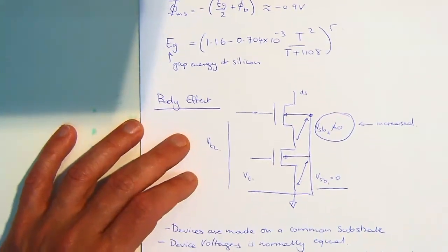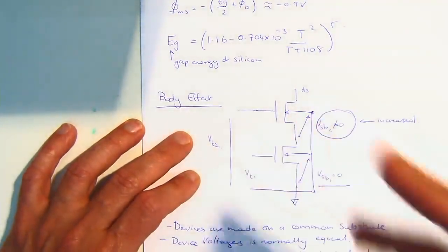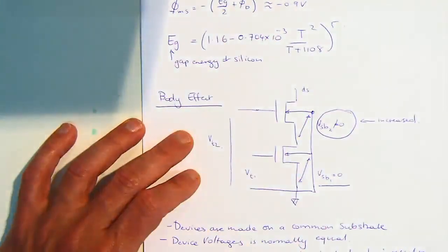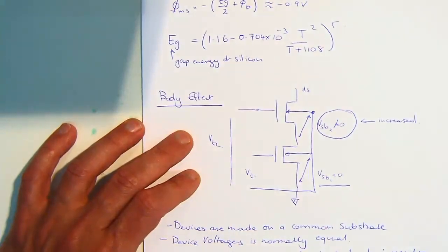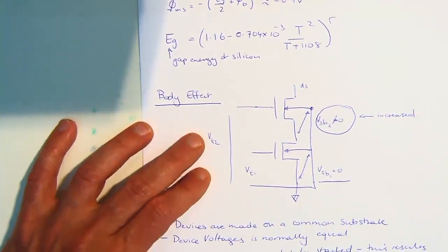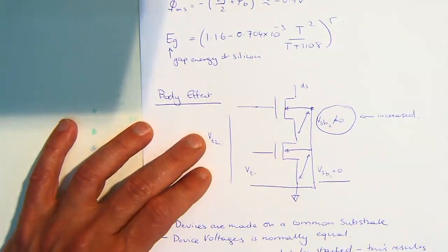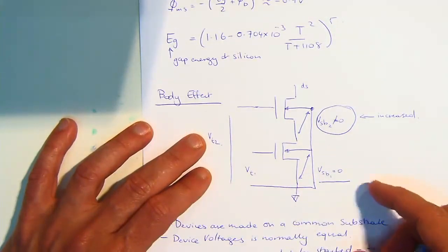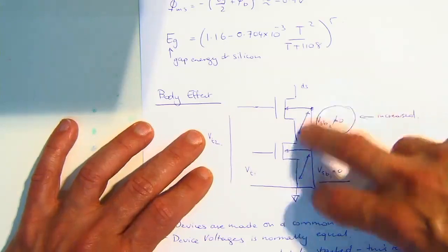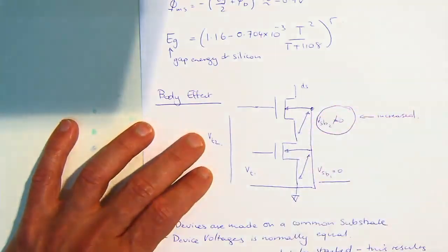In certain gates, we actually stack multiple transistors to build that specific structure. As your colleague has correctly pointed out, as you stack more and more transistors, you affect the threshold voltage, so you've got to be a little bit careful.